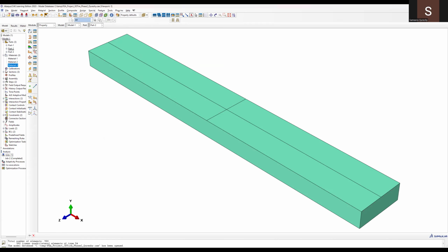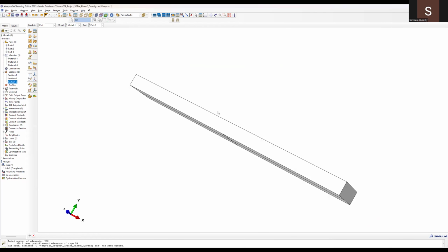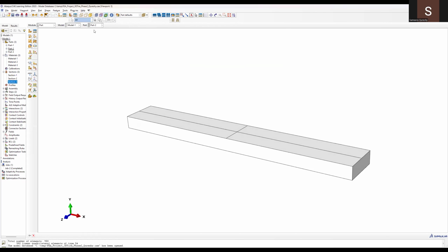So just as a heads up, the section is the same, solid homogeneous, for both the road and the wheel. You'll notice the road and the wheel are almost simple because they're just solid extrusions with solid homogeneous sections. It's just because they're fairly rigid parts. That's the only reason why I went simple for those parts. They're fairly rigid and have uniform geometry, so I just partitioned them into 4 quadrants basically.